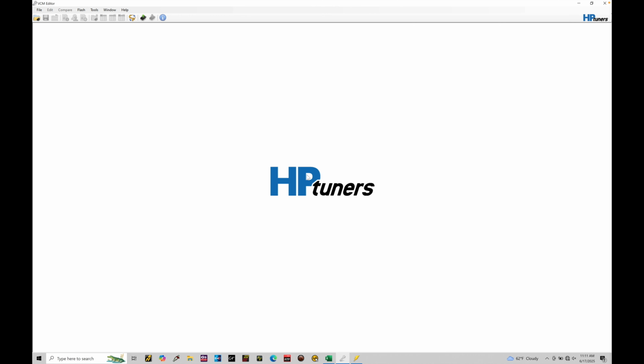I'm going to go through the tables and how everything interfaces here in this tutorial. Rarely do we have to change things in here, but there's some situations where you may have to go in and edit and change a few things within the programming. For example, if you're coming on and off the throttle and you're noticing maybe it's a little bit jerky, you may need to go in and edit some of the torque ratios in the clips so that it doesn't pull as much spark timing coming on and off the throttle.